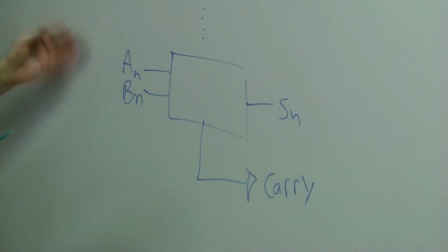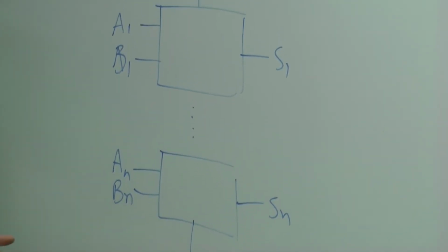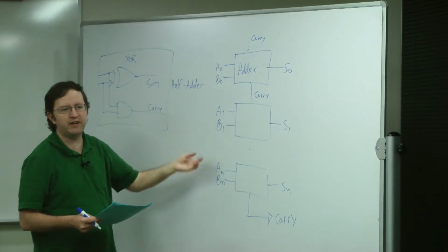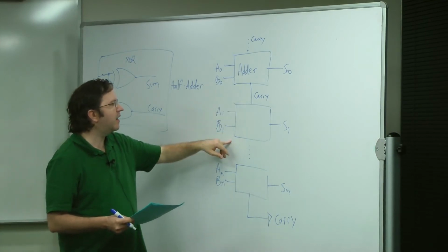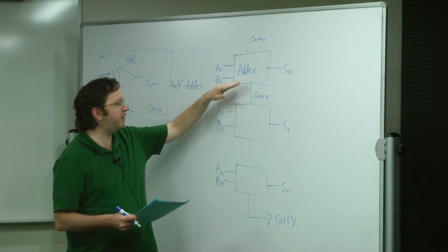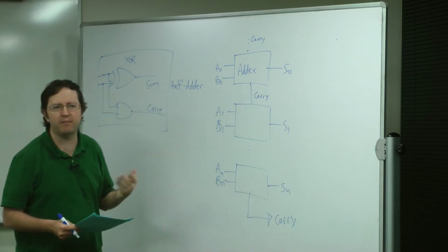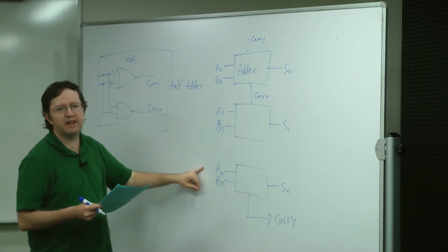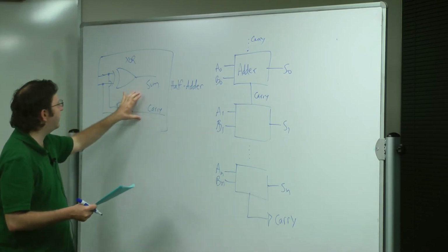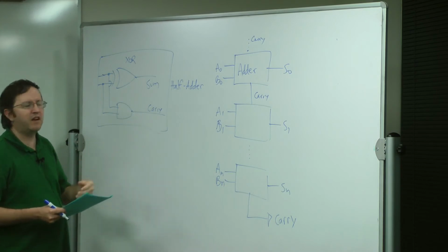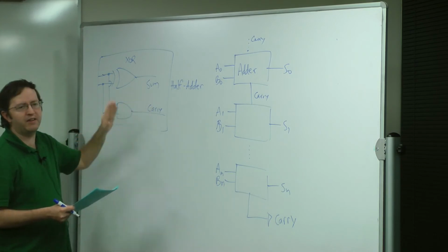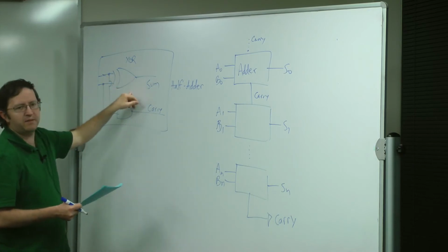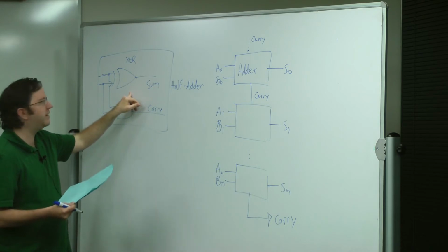Now, this is called a ripple adder, and it's probably the simplest of adders, but it also has a disadvantage in that it takes a while for a single sum to basically ripple all the way through in order to get the final answer. So this has been the subject of a lot of optimization. It's my understanding there are circuits that get the original circuit all the way down to just 8 transistors, which is a lot more complicated than the typical exclusive OR circuit I'd drawn earlier.